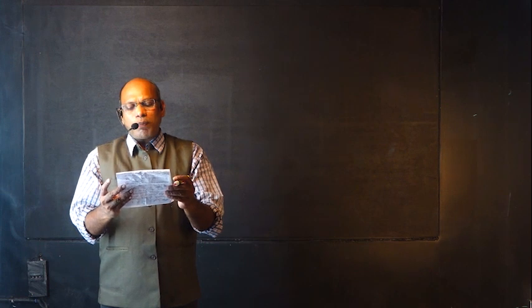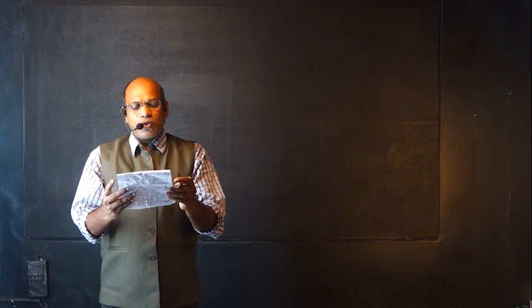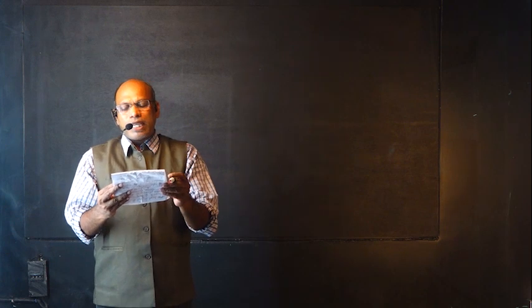A circular solid plate of diameter 150 mm is placed in the pipe to obstruct the flow. Find the loss of head due to obstruction in the pipe. Coefficient of contraction equal to 0.62.